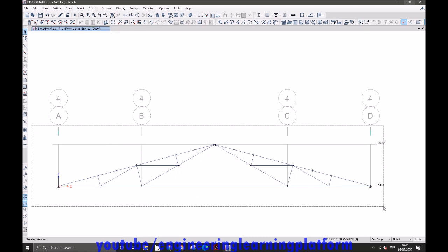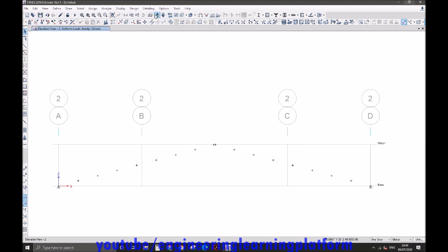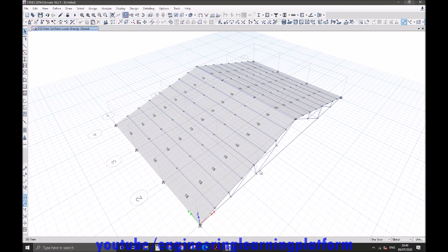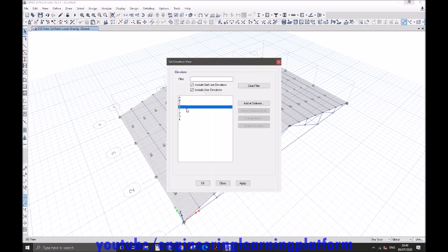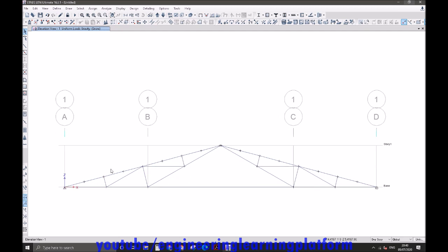So if you notice, the top chords are still broken at the purlins, which is not the real case. So I need to join all the top chords. So I am deleting the rest of the purlins, or you may call them trusses. I'll do the modification in a single truss and then replicate them again. This could have been done in earlier steps, but then I would not have gotten these points for joining the purlins, though that step was necessary. This is how steel modeling is done.